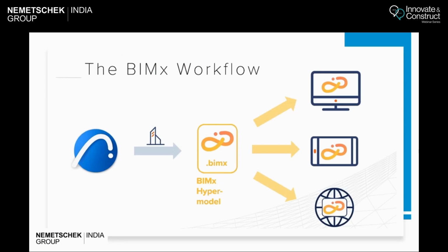So basically how BIMx works is that from the authoring tool, once the model is done, you export it through a hypermodel, which is the .BIMx file. Then this file can be directly opened on your BIMx desktop app, on your mobile devices, or on the web interfaces as well.